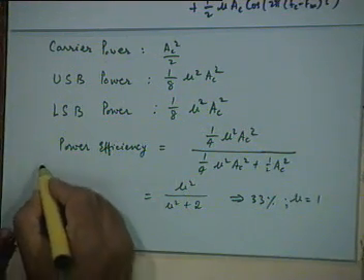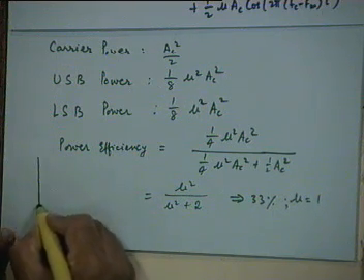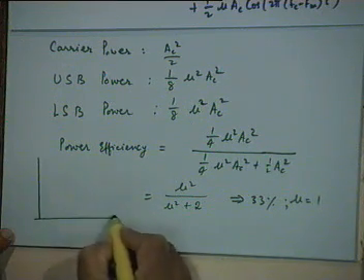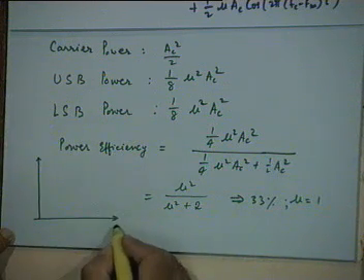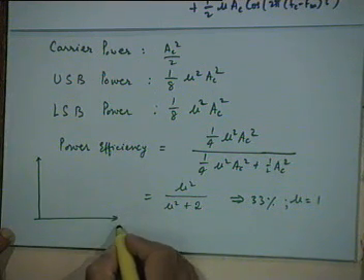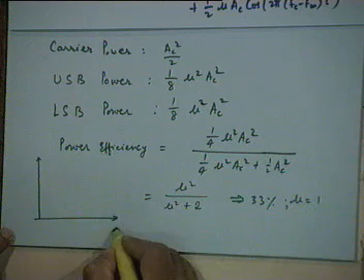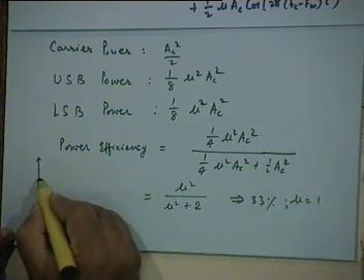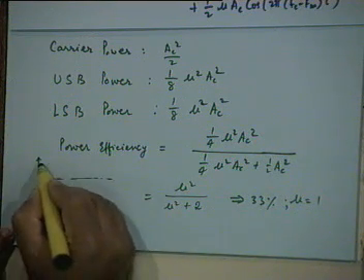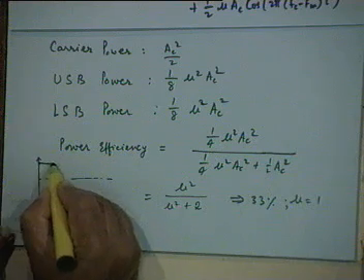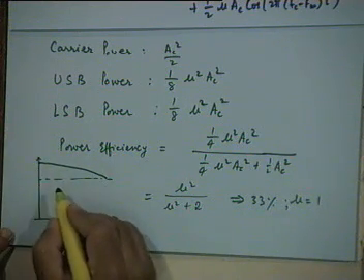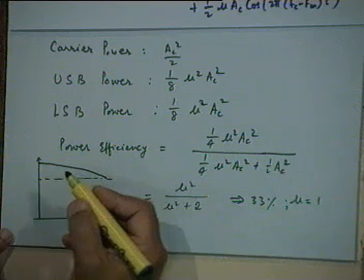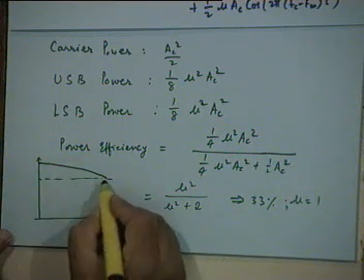Okay. So if you were to plot, in the form of a picture, not power efficiency but the various powers that we had talked about as a function of mu, the profile of the carrier power comes down like that, right? If you have mu equal to 0, all the power is in the carrier, right?